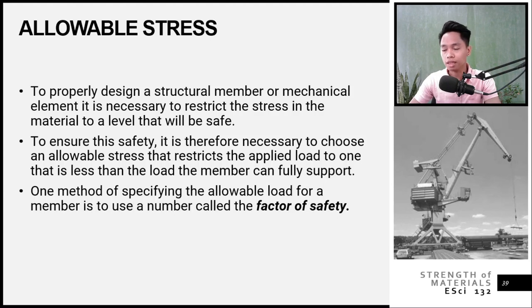Safety is the priority. To ensure safety, it is therefore necessary to choose an allowable stress that restricts the applied load to one that is less than the load the member can fully support. What does it mean? If you are going to analyze a structure, you cannot just use whatever load is there; you should have allowances.